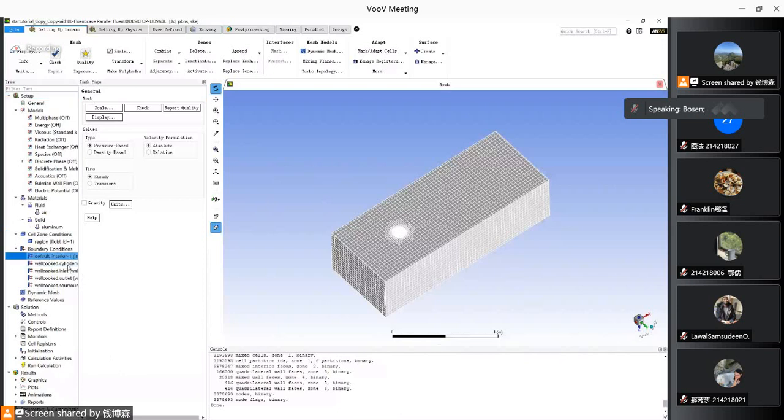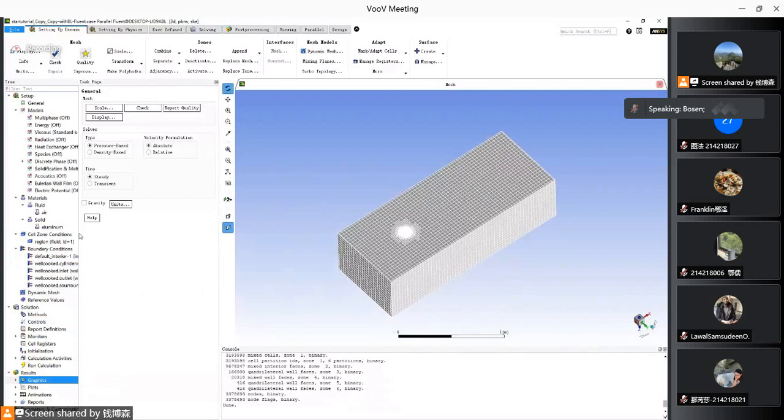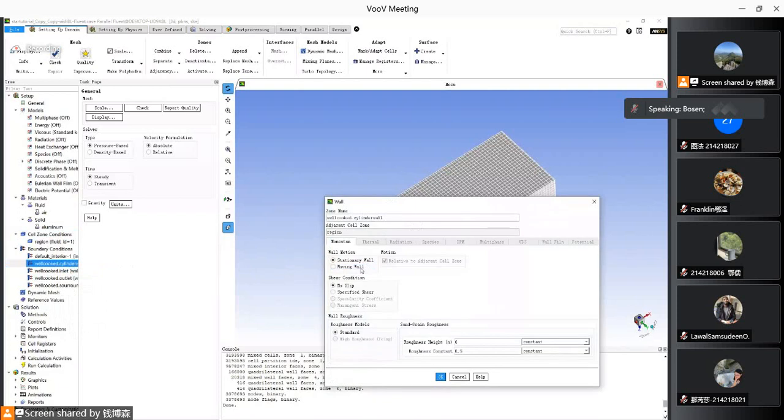So this is a cylinder wall boundary. I'm sorry, I don't know why it just wouldn't go further to the left. It's really annoying, but try to deal with it. So this is a cylinder wall boundary. Let's right click on it and click on edit. Here we have a stationary wall, moving wall, and a slipping wall, no slip wall.